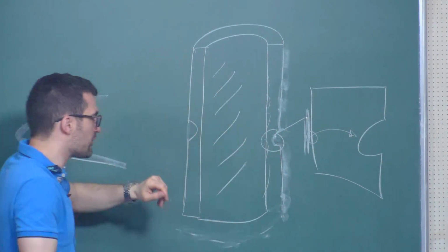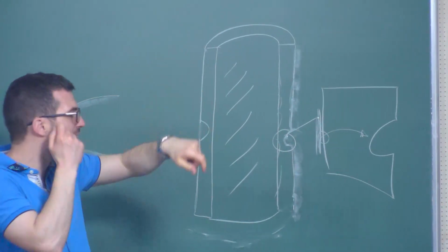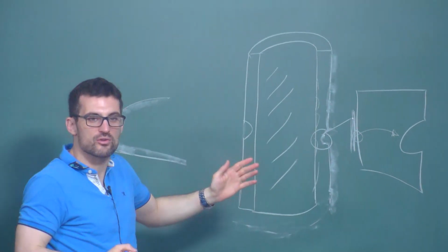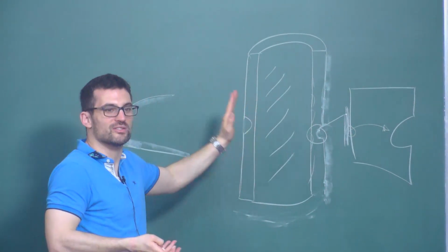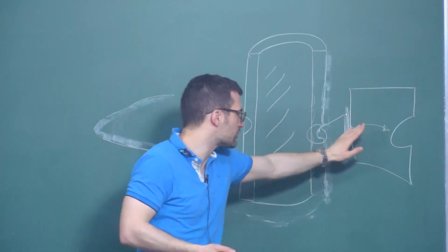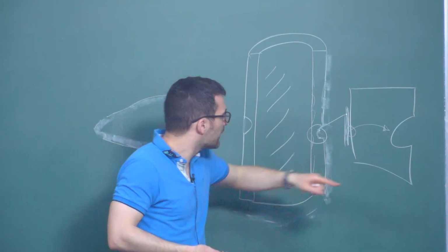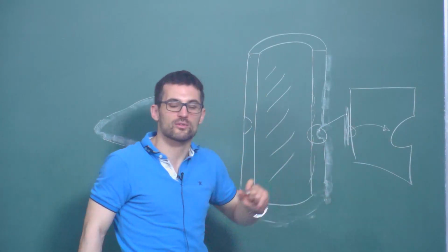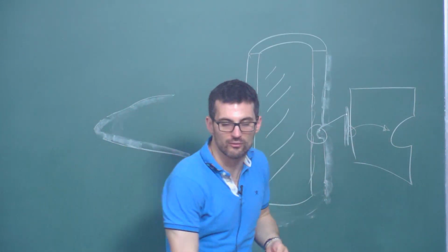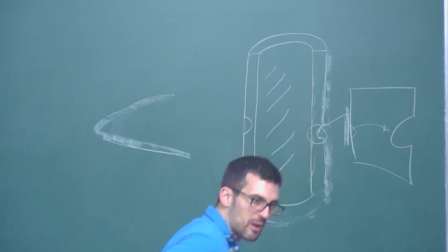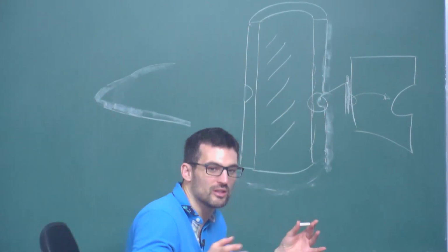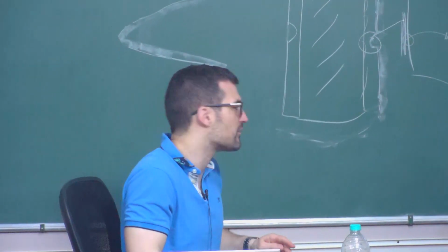So then he did a set of experiments and basically held the load constant and saw how long it took to fracture and where fracture occurred, whether it started in the inside or the outside. And it was a very clever set of experiments, and actually fracture occurred here. So he concluded that hydrogen was dominant in environmentally assisted cracking of aluminum alloys, and this was a landmark paper for the field, and the community switched their attention to hydrogen because of this.